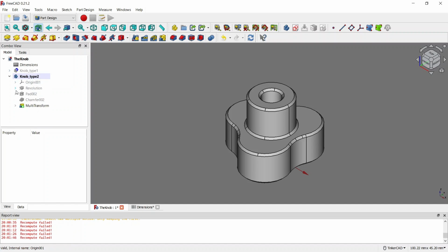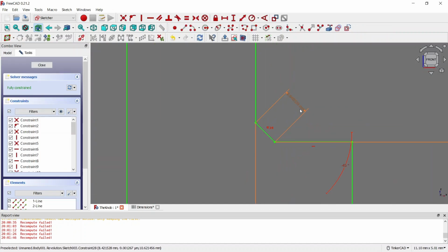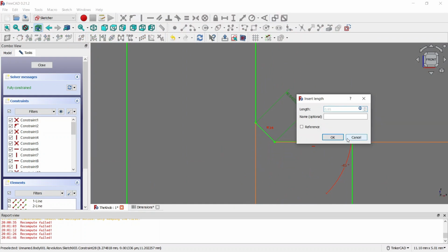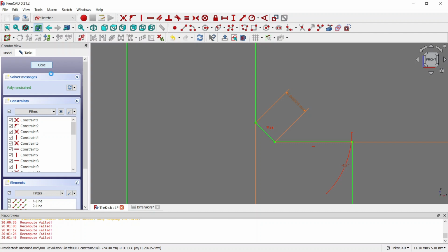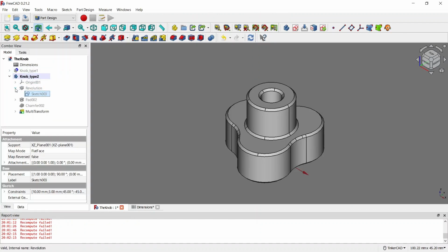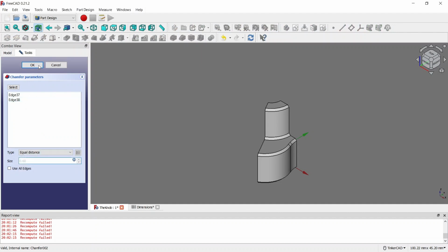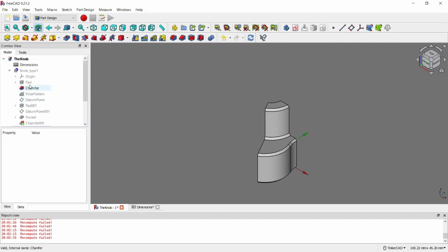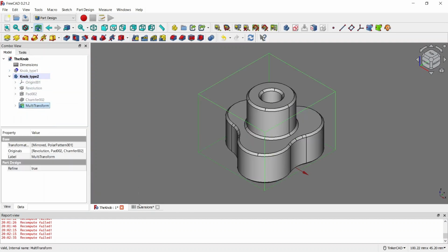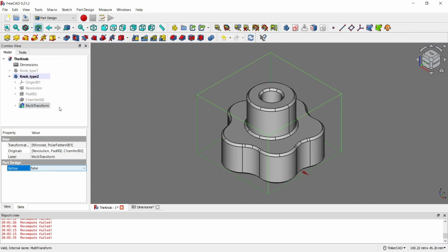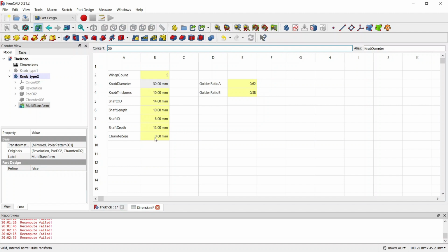But if you want to have it adjustable, so again parametric design, then you have to change those values to the one defined in a spreadsheet, and this is basically the only change we need to do in here. Now the length of references need to be adjusted, and changing the chamfer size. I thought that using a refine here takes a lot of resources of the PC, but it was something else, so we could leave the refine on true. It just takes a lot of time.